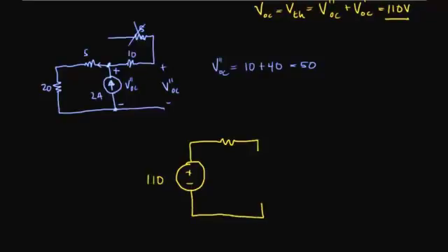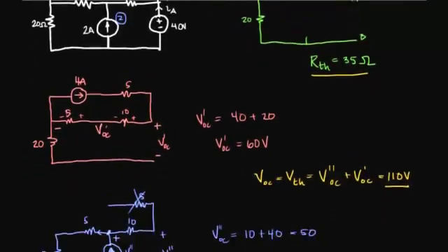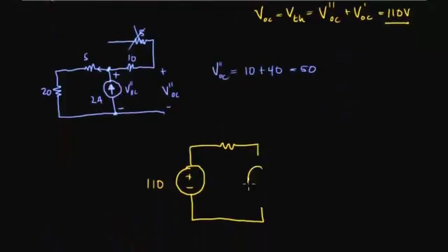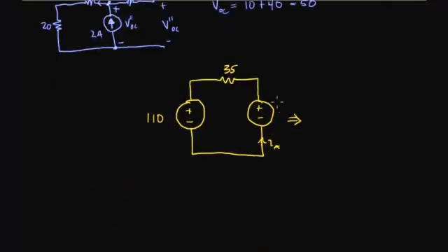And what is it we're putting in here? We're putting a 40-volt voltage source and we're looking for IA. So what I'm going to do, just to simplify this here, and this is 35, is I'll combine these two voltage sources. So that's going to be 110 minus, what was that number again? 40. Okay, minus 40. And so that'll be 70. Okay, so it'll look like this.